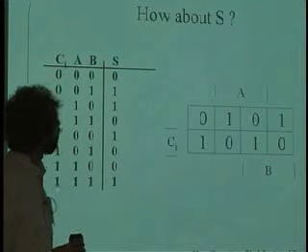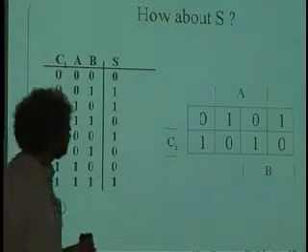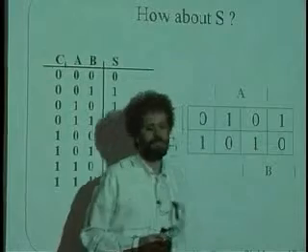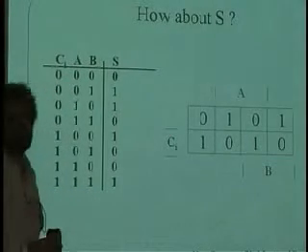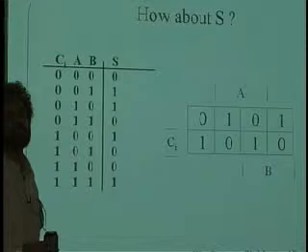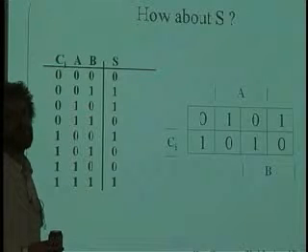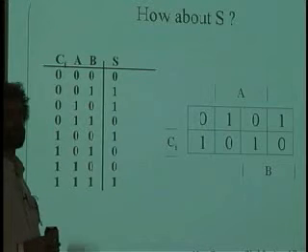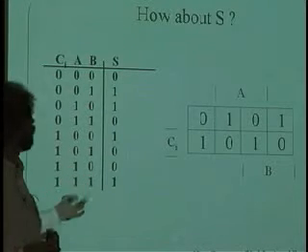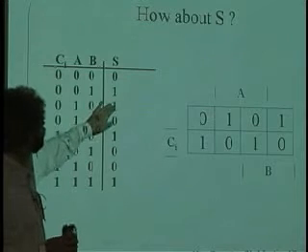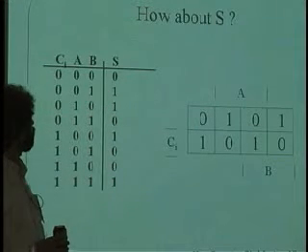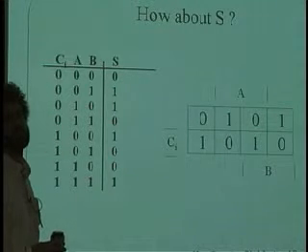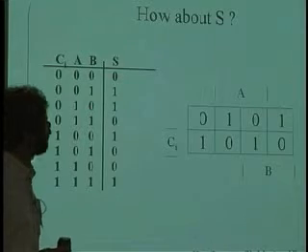And so in order to generate this, I have to basically put a circle around every single one of these ones, and then I have to ask myself the question, can I coalesce them into bigger terms? And the answer is no, I can't. So I can't make a sum of products form that's any more simple than having 4 terms, which we saw at the very start, which take into account the individual rows where S is 1. Because this is basically saying, is the number of ones in the input odd? That is what S is, and so it's exactly the parity function.